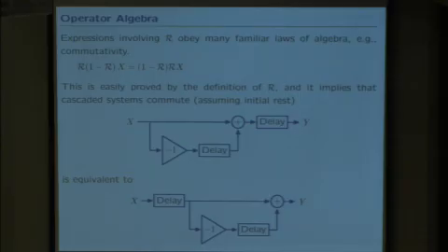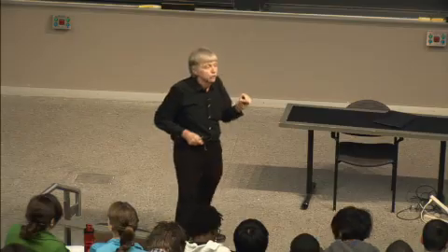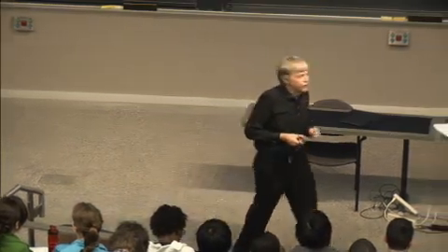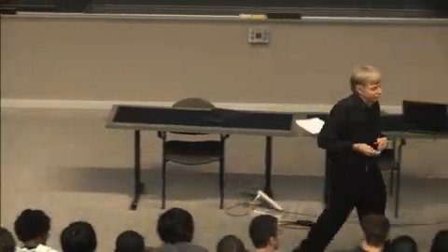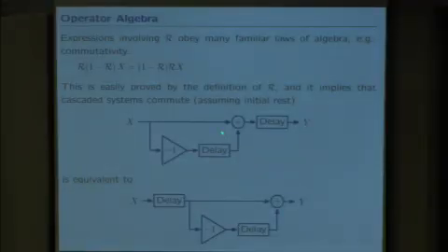You remember that I said one of the powers of the block diagram representation is that we can look at signal flow paths. We can use that as a way of proving things. This system has two signal flow paths, the one that goes straight through that way and the one that goes down this way and up that way. Because of the addition, the adder just adds the result of those two flow paths. So the first flow path introduces one delay. The second flow path inverts and puts in two delays.